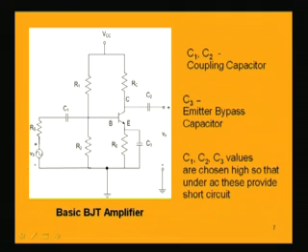That means, we must get at the output an amplified distortionless signal, and this resistance Rs is basically a series resistance which is present in the source in series with it, and it should be very small. Ideally it should be 0, but it is not true that it will be 0, because practically there is a small resistance in series with all the sources, that is denoted by this Rs.